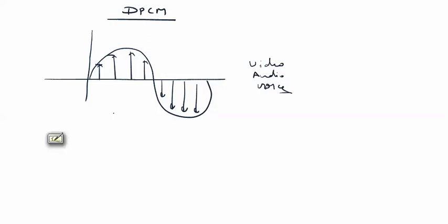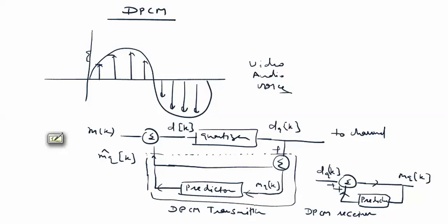For transmission of the difference between two successive samples, we have to add a memory element in the PCM device. Via this scheme we reduce the redundancy and save the number of bits in a particular cycle. If bits are saved, we are saving bandwidth. The block diagram for DPCM is the DPCM transmitter and receiver. The receiver is the lower portion of the transmitter.